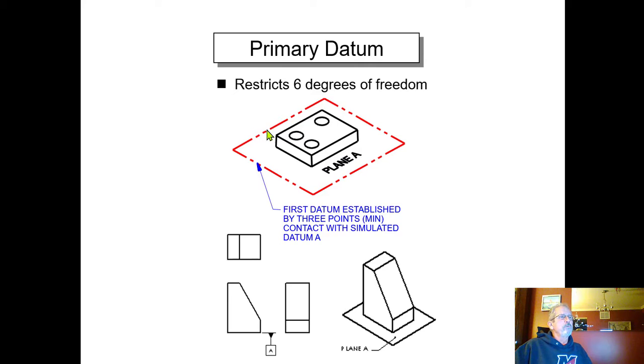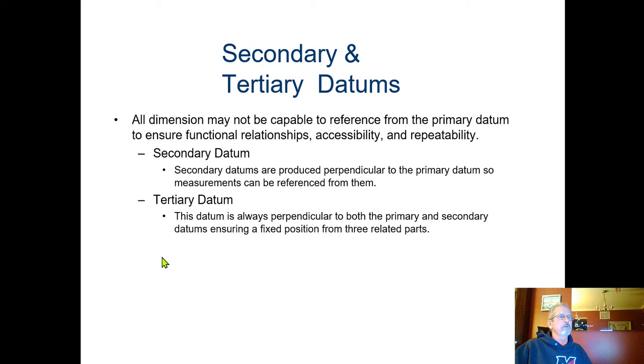All right. So if we take a look at this object right here, it's in its natural resting position like this. Here's the front view, natural resting position. That is a good flat surface, which means it's a good surface to measure off of. So therefore, what we're going to do is call this out as being datum A. So that's the most important surface.